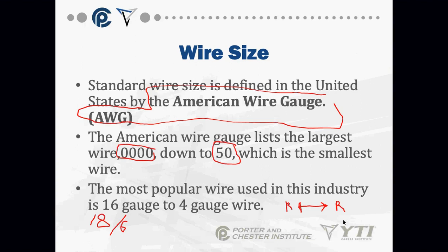When I was doing a ton of installation work and a ton of control work, because the contractor I worked for, I was the controls guy. I went out to every job and did the control work. I normally kept 2 of the large boxes of Cat 5 wiring, a couple of 500-foot spools of 18-6 and 18-12, and about 500 feet of various colors of 14 gauge and 12 gauge wire.